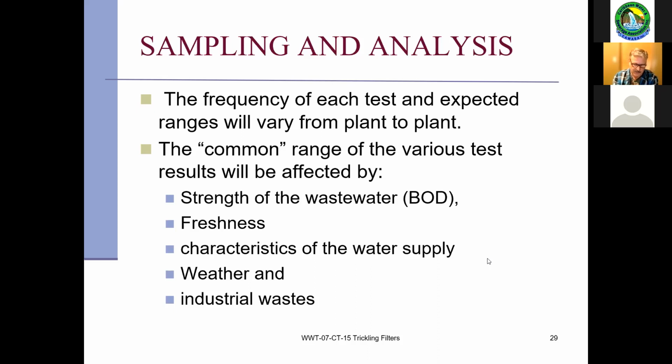For example, there was one that we used to operate at a ski hill, so it's out in the cold. It was covered. It worked really well. Unfortunately, with that one you could see the difference because there is no equalization tank or way to stop the high loads or high flows coming in. Although it did work well, there were certain areas, as there was a lot of people there, where the flows coming in were actually washing out part of that filter and pushing that biomass right through.